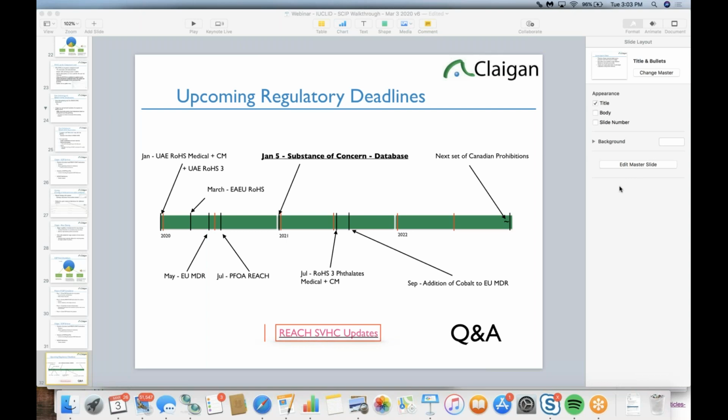I have an off-the-shelf resistor on my product. Do I have to do a separate submission on it, or can I link it to the submission done by a supplier of the resistor? You can do both, but unless using lead solder, it's not declarable, SVHC. I would not link to the submission of the supplier because your resistor is a jelly bean part for the most part, and there could be 3 alternative suppliers for it. If it was a leaded resistor, using lead solder, I would actually just create one for lead solder because the board's leaded, and just have a lead solder listing. And lead oxide in a resistor is not an SVHC. It's leaded glass.